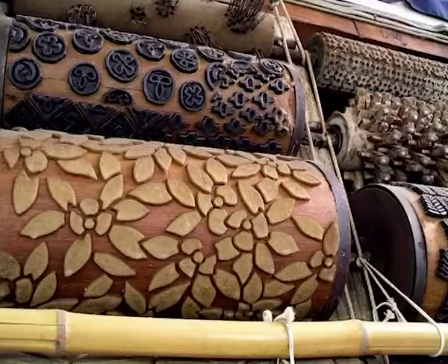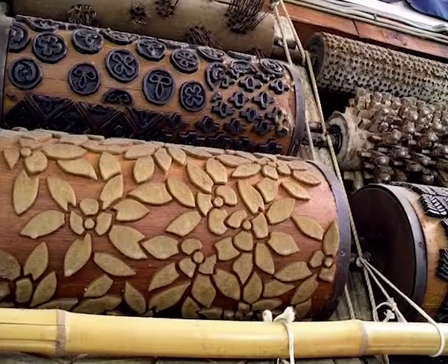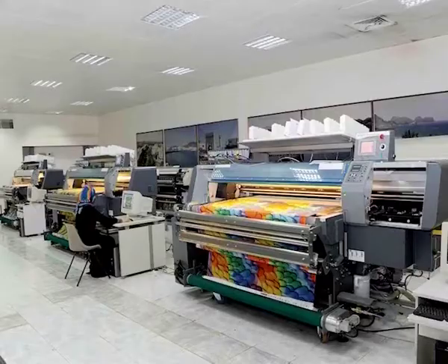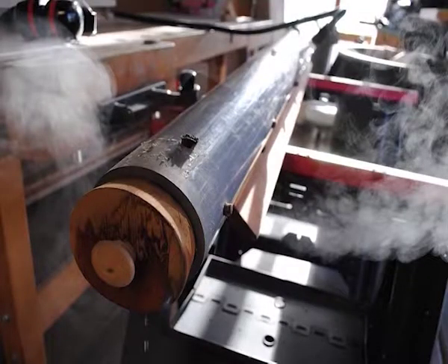Block printing. The designs are carved on a wooden or a metal block and the paste dye stuff is applied to the design on the face of the block. The block is pressed down firmly by hand on the surface of the fabric. Roller printing. In this machine, counterpart of the block printing, engraved copper cylinders or rollers are used in place of hand carved blocks. With each revolution of the roller, a repeat of the design is printed. Printed cloth is passed to a drying and then a steaming chamber where the moisture and heat sets the dye.